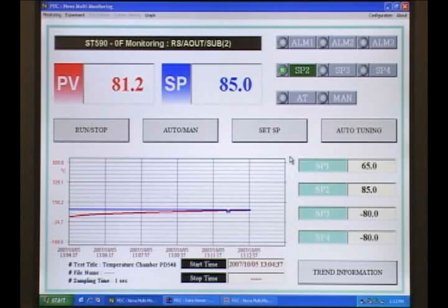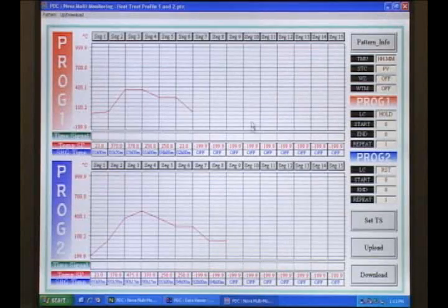The screen you see here is specific for a PD540 series basic PID controller. If I were using a 550 series ramp and soak controller, then I'd have the ability to run or reset or hold any of the 2 programs the controller can store. For that sort of controller, there's a convenient program builder that allows you to set up your ramp and soak segments all using the software, save them to your computer, and download them to or from the PD550 series model.